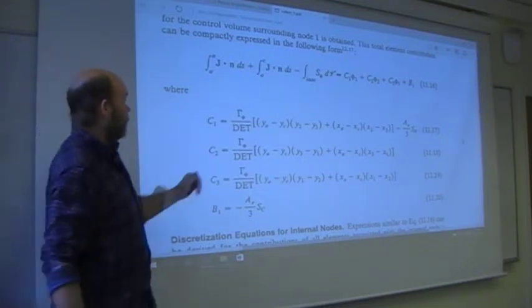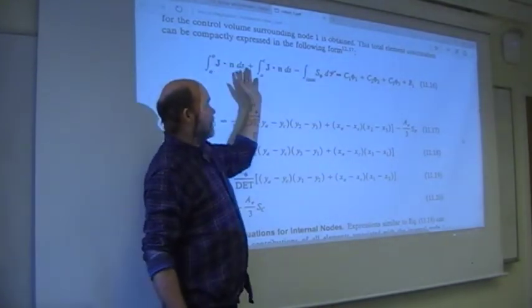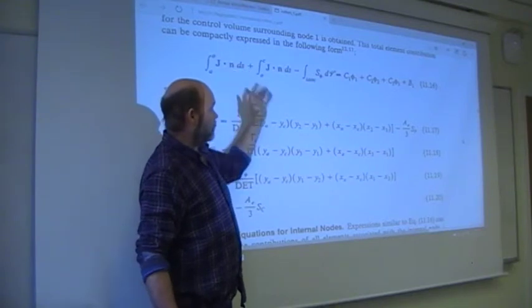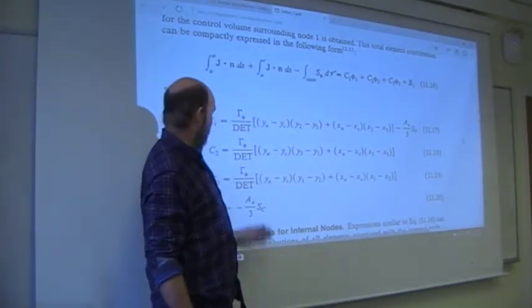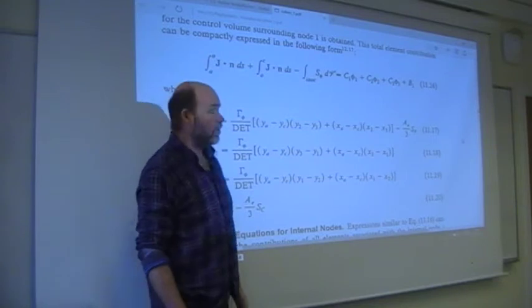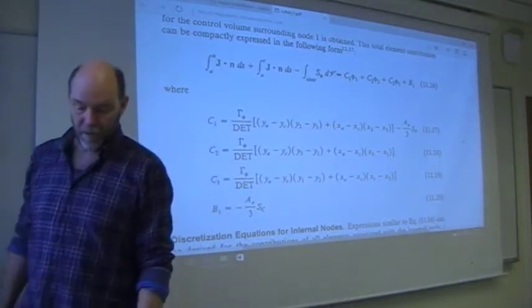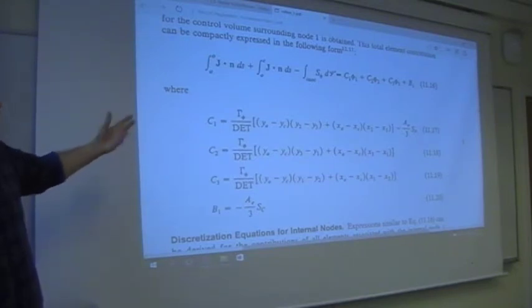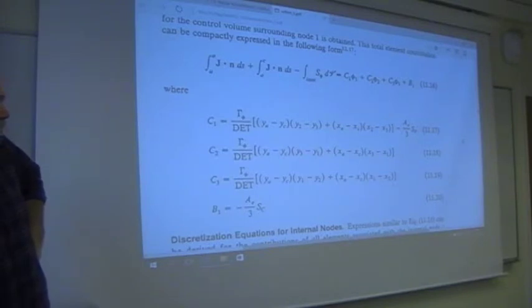Then of course it's very rapid to evaluate these fluxes. A little bit of memory of course for one triangle. You have these numbers you have to store, but fairly easy calculation. Of course, if you are talking about moving meshes, deformable meshes, then you have to redo this calculation every time you change the mesh. But for a fixed mesh, quite efficient.